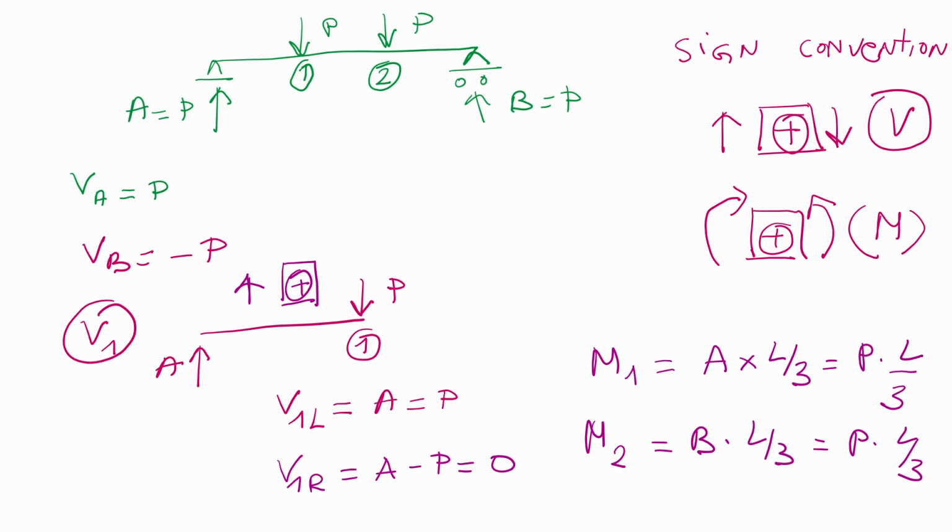So this is the first step. The second step will be to determine the internal forces at each relevant point along the beam. So, sign convention. We have shear force. If you are cutting from the left, your positive will be vertical up. If you are cutting from the right side, your positive shear will be vertical down, or shear force tends to slide the cross section.